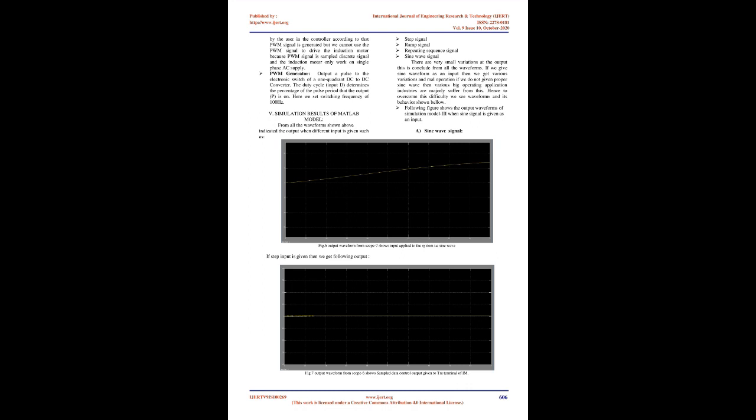Starting parameters are as we discussed in the model, given below. AC voltage supply: here we are using a single phase AC voltage supply with a peak amplitude of 110*sqrt(2) V and a frequency of 60 Hz. Rectifier: here we are using a rectifier with a forward voltage of 0.8 V and an internal resistance of 100 ohm.